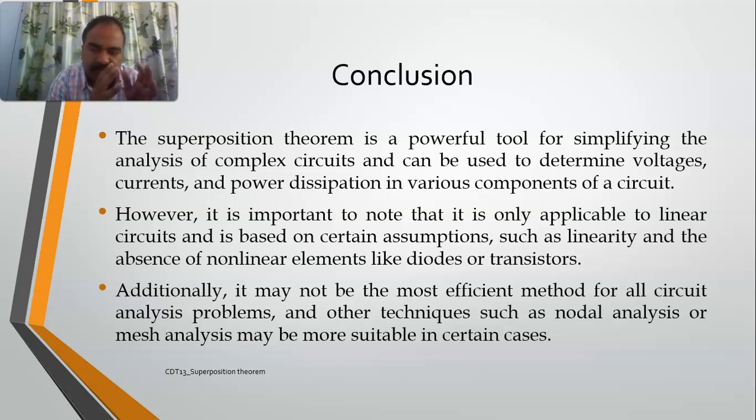Most of the time, when the number of sources and elements is small, you don't need the superposition theorem. You don't want to calculate individual responses and then sum up. You can directly go with nodal or mesh analysis. But if the sources are too many and you want to determine individual contributions, then superposition theorem is better.